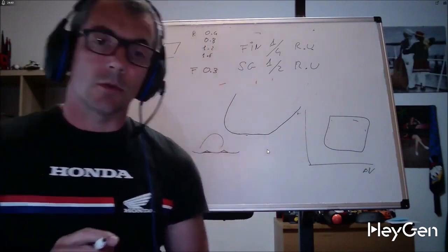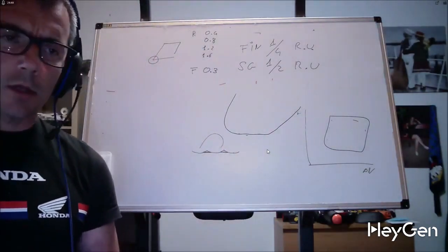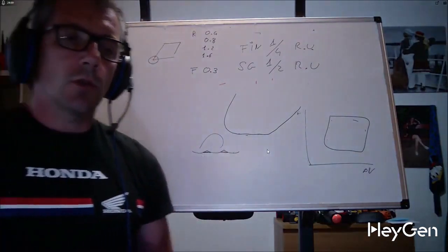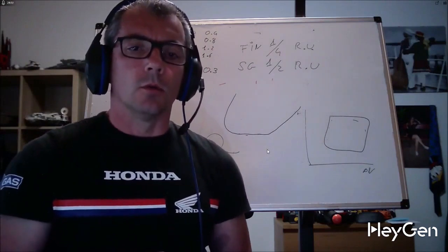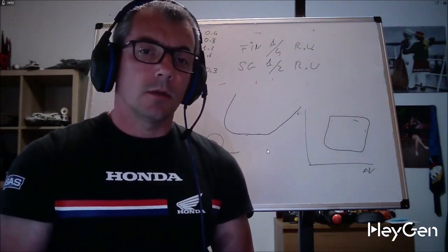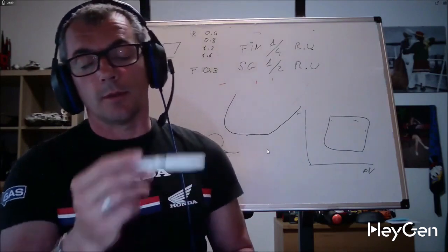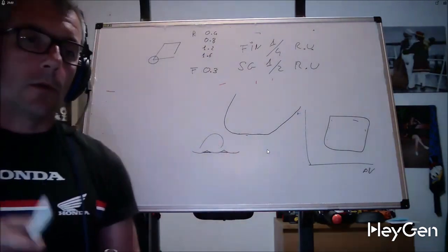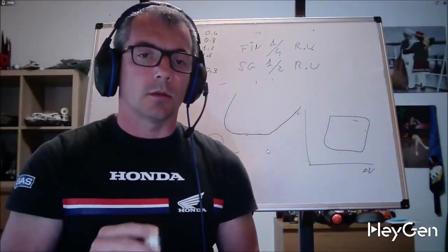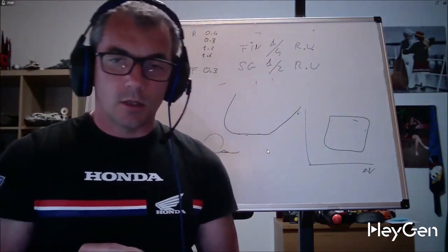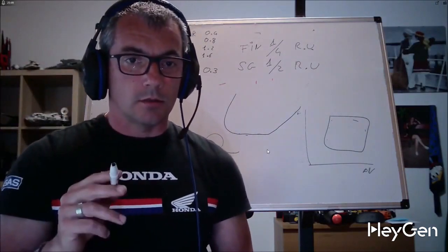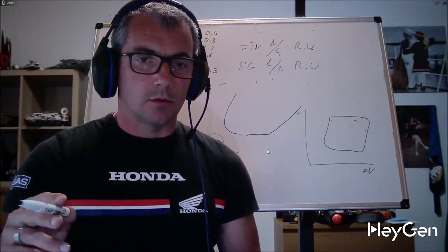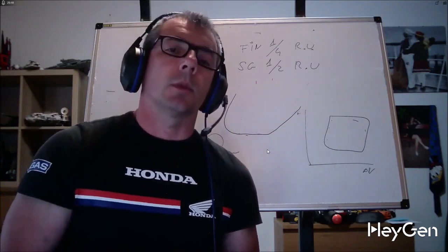Let's start. If I don't think of anything else, because sometimes I come up with something and add some more information, let's begin to look at sensible programming. So not starting from x0, z0 with some offset. Let's start to see some roughing macros, which are very interesting, and you'll see how roughing macros make life easier. And remember one thing, for now, we haven't talked about it, but if you don't clamp the part well, you can create the best program in the world, and you'll only get garbage from your machines.